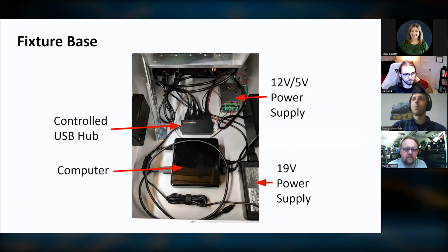Yeah, so this is typically part of the test specification development, where you generate a series of test cases, and the idea with each of those test cases is you're testing some part on that circuit board. Say there's a 5-volt voltage regulator that you're testing. So you read a voltage from the 5-volt line. You want to make sure it's 5 volts plus or minus 1% or something like that.